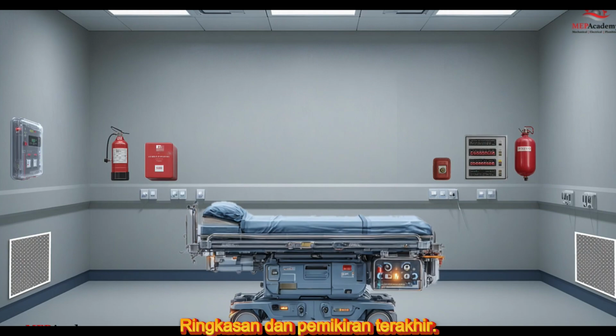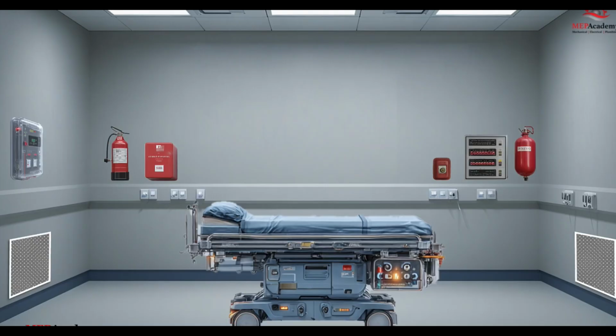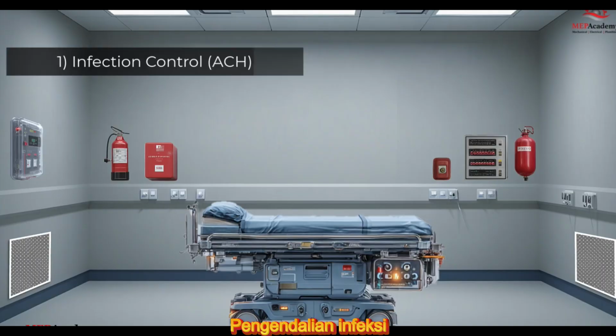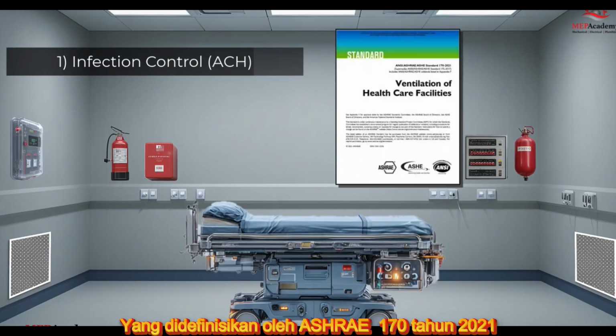Recap and final thoughts. To summarize, a hospital operating room HVAC system isn't just about heating and cooling. It's a critical infection control tool. Let's quickly review the 4 key takeaways. 1. Infection control. HVAC systems prevent surgical site infections using HEPA filtration and airflow control by requiring a minimum air change rate, which is defined by ASHRAE 170/2021.